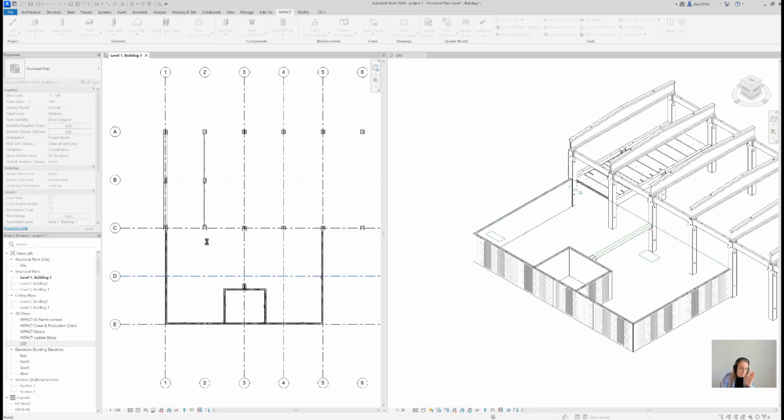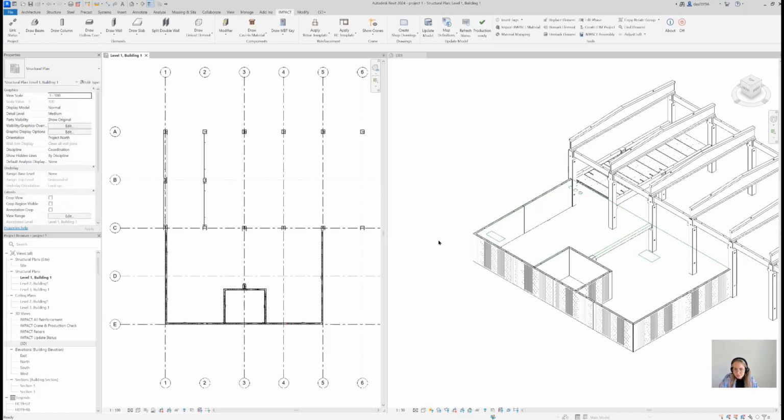I'm going to do 2 symmetric gables. And here I'm going to press escape and a 6 millimeter gap. So we can follow it here. The wall is being split. So we're about to get some pretty good looking double walls here.